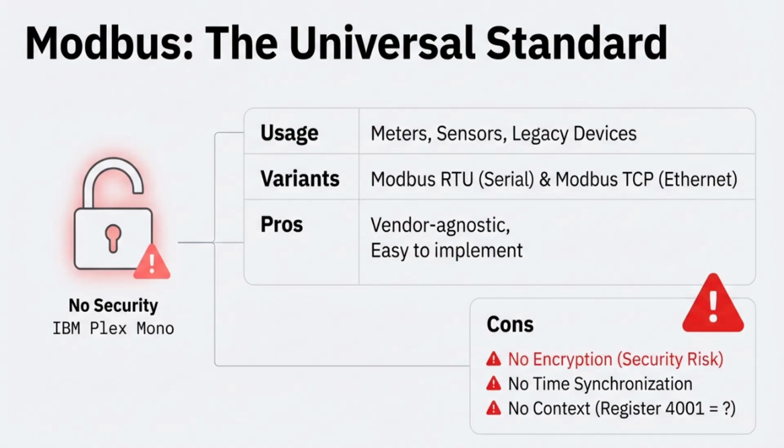It is much easier to implement compared to the earlier protocols. The skill set required to implement Modbus is very little, and we will get engineers who know Modbus and its implementation. Basically, we can find a lot of installations having Modbus, even in industry or in substations and so on, right? So this is the strength, and yes, the limitations we already spoke about.